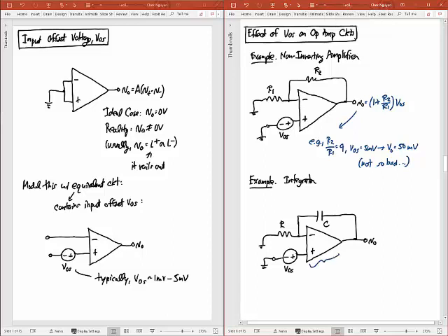So this is ideal, and this models the non-ideality. Okay, and same thing for resistors too. I would use an ideal op-amp, then I put the resistor on the outside, the other resistor on the outside, if you really wanted to explicitly show that. But that's probably the best way to handle problems like this.